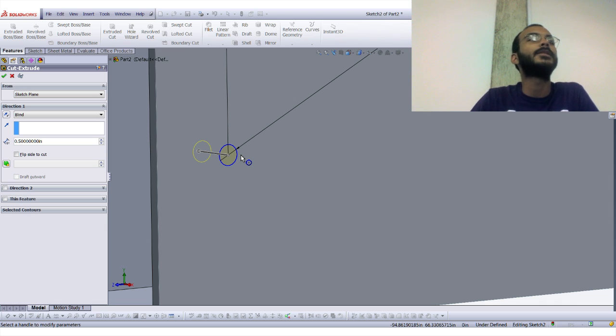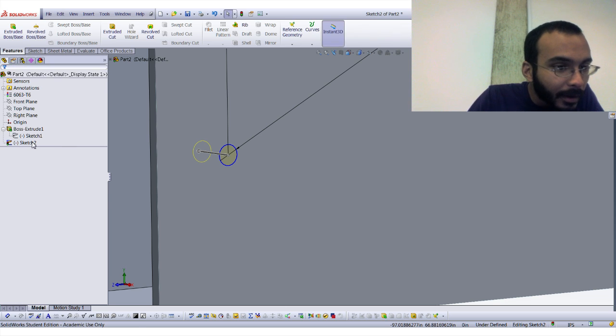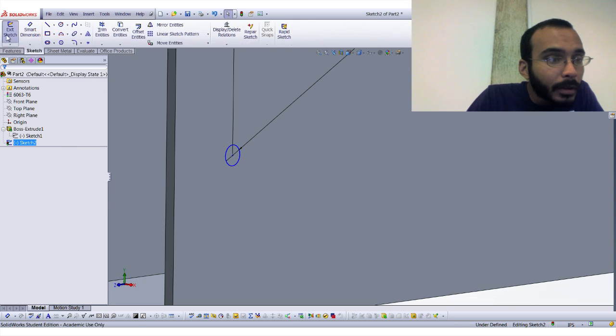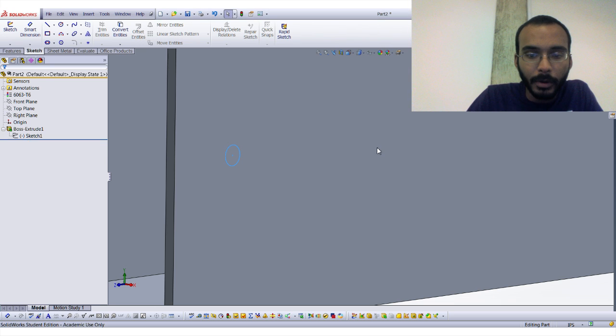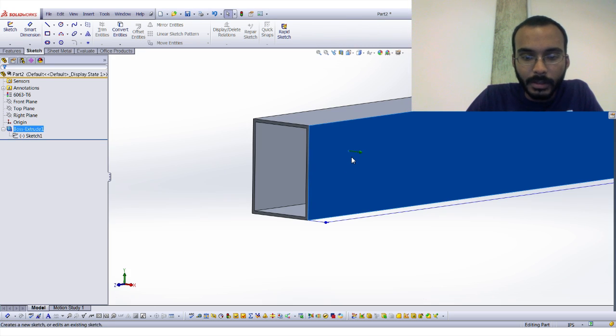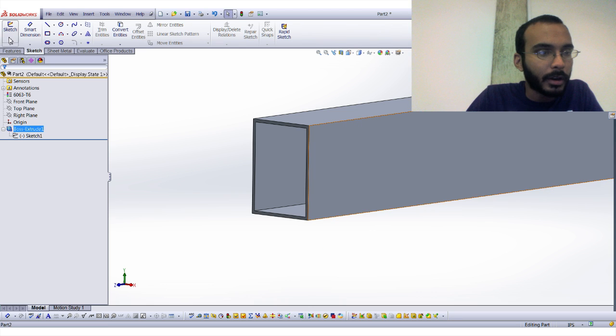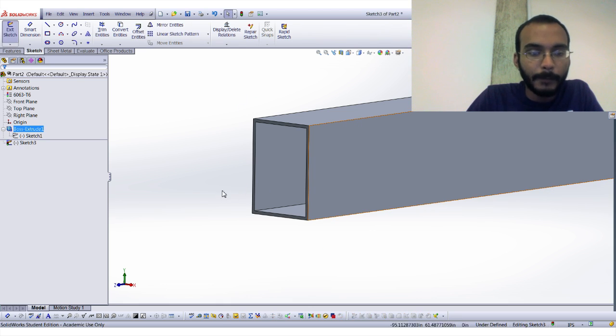Where are we at? We have a question? Question? How do you do that? I'll go back. Okay, so let me get out of here. If you're on the side of a part somewhere, you can either right-click and hit Sketch with a little sketch button right there, or you can click on it and hit the sketch button up in the top too. What sketch button? Do you mean the 3D sketch on plane?